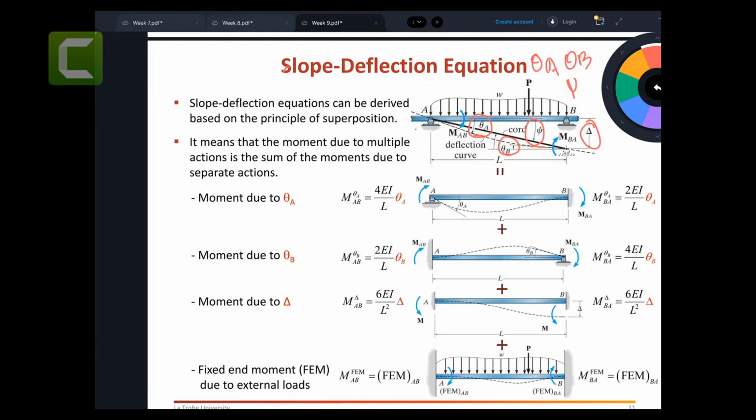Now, as you know, in the force method, we did something similar: when you find the static equilibrium equation equal to 1, then we make a primary structure by removing that one force. And we say now this structure is statically determinate, and now we use our conventional methods. We can do the same thing here.